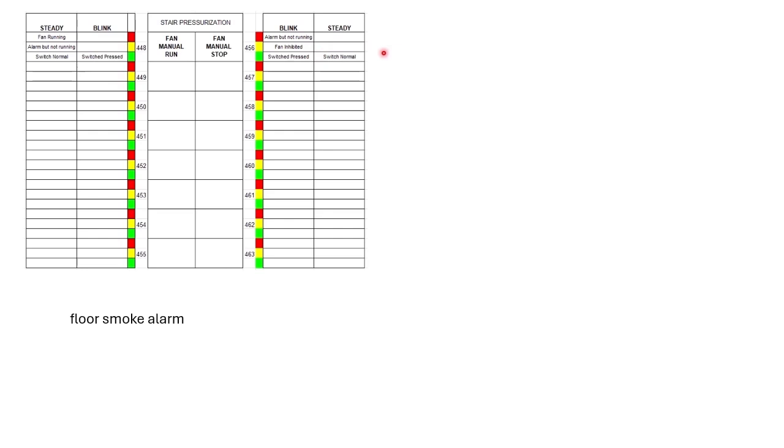So we'll start with our equation that we're going to use for group 151 to control that module. So we know that it needs to activate on a smoke alarm on one of the floors and not a stairwell detector or the manual stop. Now there's a little error here that we need to correct, because the way this will actually operate is it will activate the fan